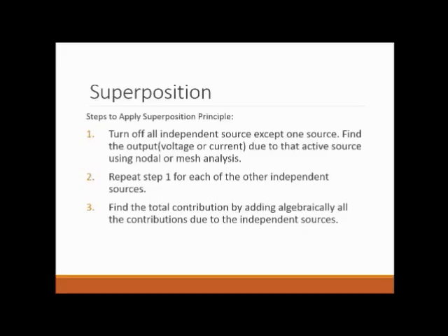Now to follow this superposition theorem, there are several steps to apply. The first step is to turn off all the independent sources except one source. Find the output voltage or current that is due to the active source using nodal or mesh analysis. Then you need to repeat the first step for each of the other independent sources. Now find the total contribution by adding algebraically all the contributions due to the independent sources.